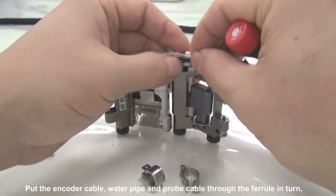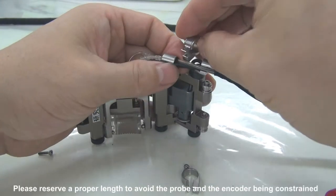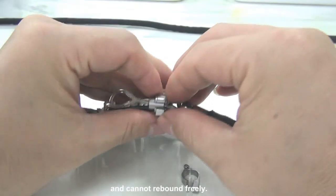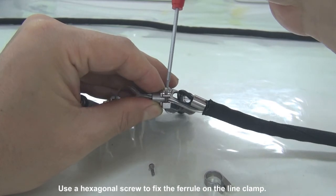Put the encoder cable, pipe divider and probe cable through the ferrule in turn, and put the ferrule through the braided tube. Please reserve a proper length to avoid the probe and the encoder being constrained and unable to rebound freely. Use a hexagonal screw to fix the ferrule on the line clamp.